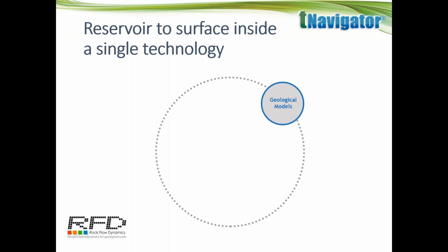So what we can do within tNavigator is we can actually go from a blank page, upload some seismic, and then do seismic interpretation, analysis on your seismic as well, building faults. Ultimately building your static model, assigning properties to your model, and then we can do things like well correlation, designing or importing your own faults, facies analysis, petrophysical modeling, and build a schedule section as well. So ultimately your aim is to build a dynamic model ready to be imported into your simulator.